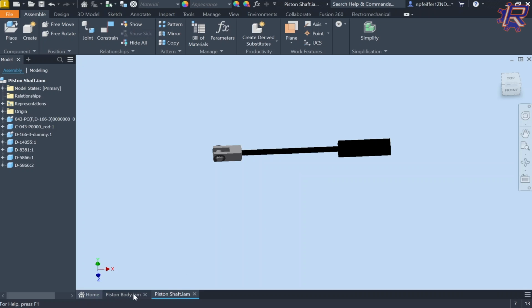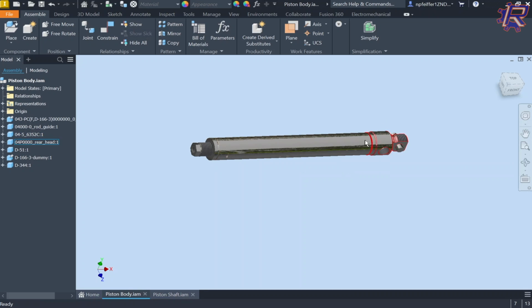And when you're constraining a piston, it's very important that you make all of the constraints in the final assembly. If I were to make an assembly, constrain the pistons, and then import that assembly into a larger assembly, the pistons wouldn't work. They wouldn't be able to move. So you need to make all of the constraints in the final assembly.